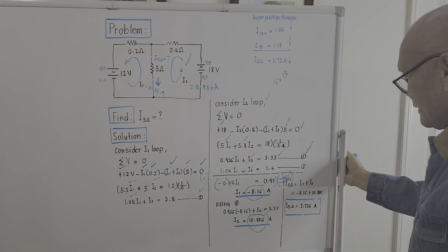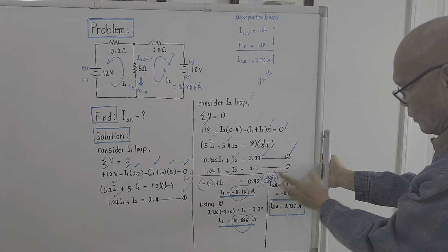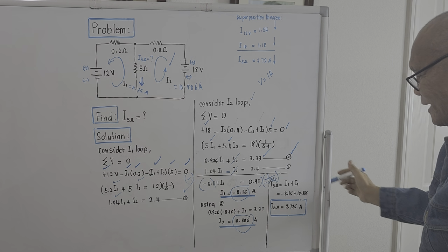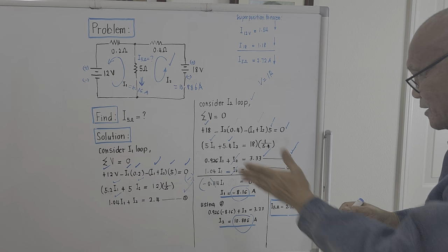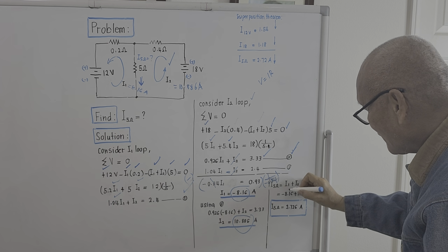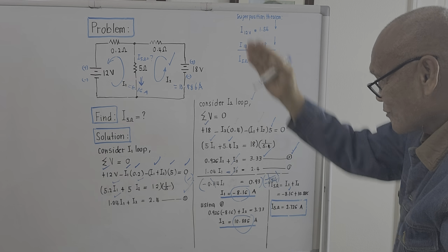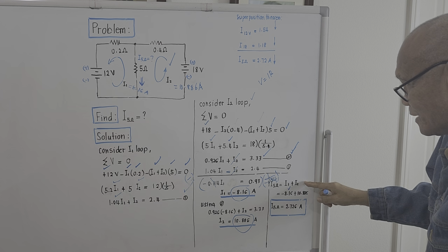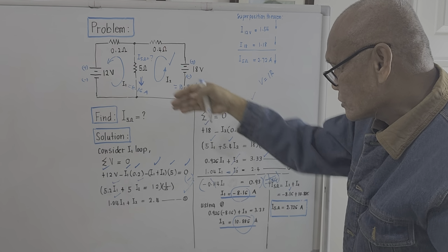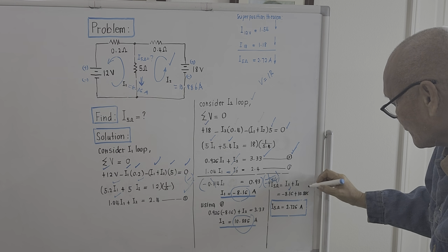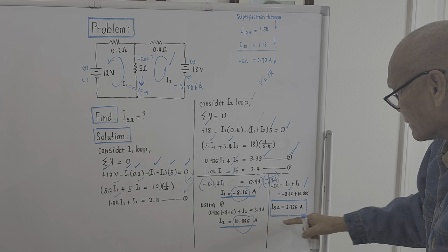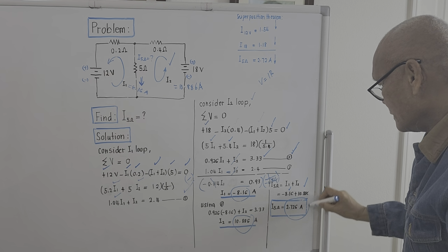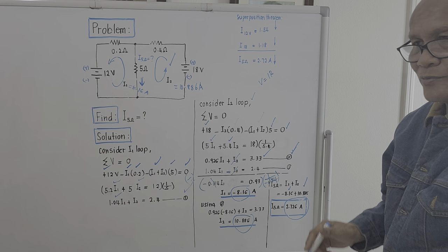So the current passing through the 5 ohm load now, well, it will still be I sub 1 plus I sub 2, but we must carry the proper sign. And the value of I sub 1 is, instead of a plus, a negative 8.16 amperes. Okay, it is upward. It is against I sub 2. The value of I sub 2, we assumed that I sub 2 was downward and it was correct. So we maintain the sign plus 10.866 amperes. And what will come out for the current passing through the 5 ohm load will be 2.726 amperes. Okay, that is by using Kirchhoff's voltage law.